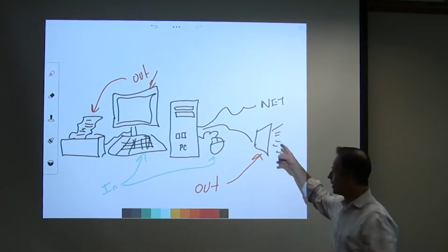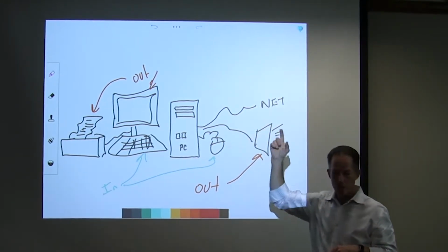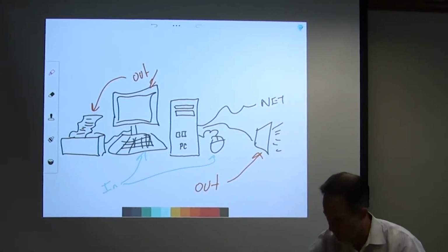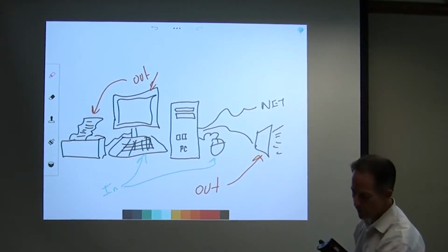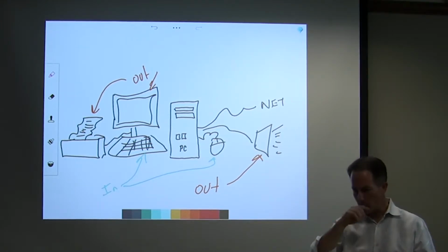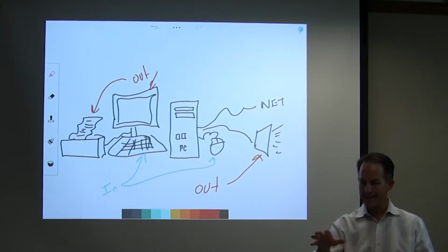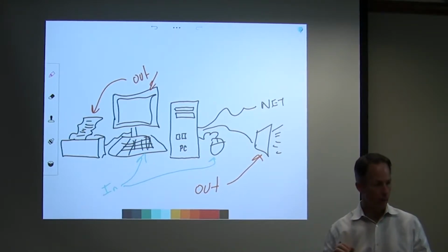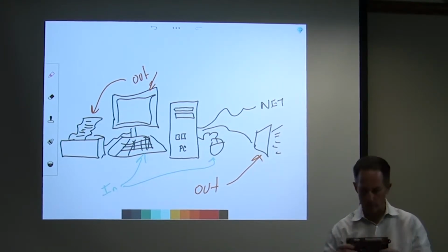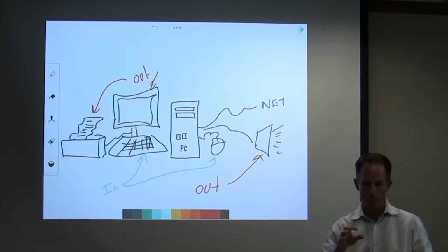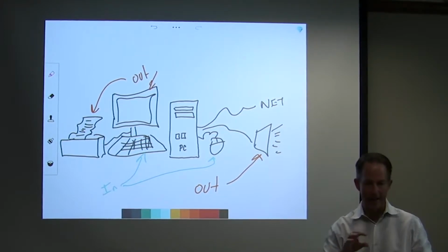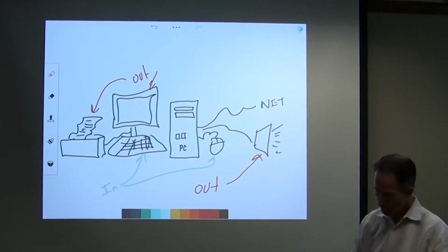So let's talk now about our network. In the controller world, when we're working with one of these controllers, whether it's Delta, Smart 2, or something else, we have network variables or network inputs and outputs. Now, you mentioned these acronyms: DI, digital input, AI, analog input. Those are how we would title them sometimes on these controllers. DO or BO, as in boy, binary output, digital output, or AO, analog output.